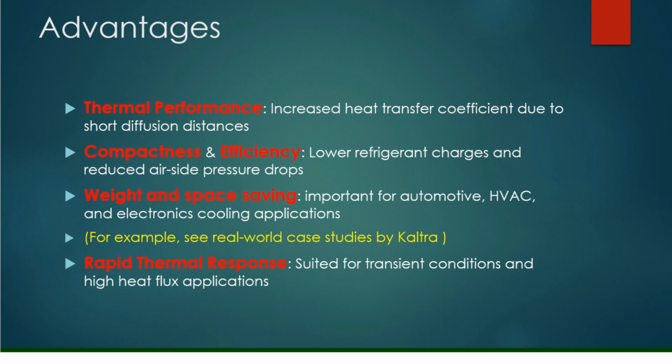The second benefit is that lower refrigerant charges and reduced air side pressure drops are benefits that you get from this. As part of the slides, I would show you some of the disadvantages or some of the problems that you can have when you are using microchannel heat exchangers, and then you would understand the whole idea of the pressure drops there.